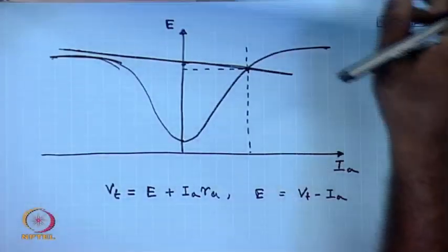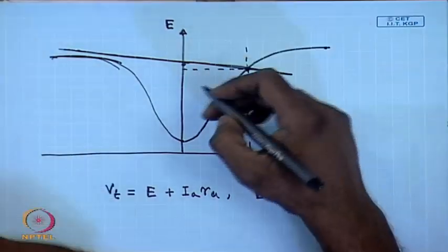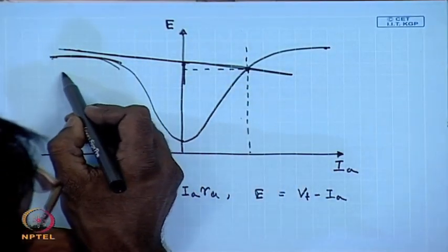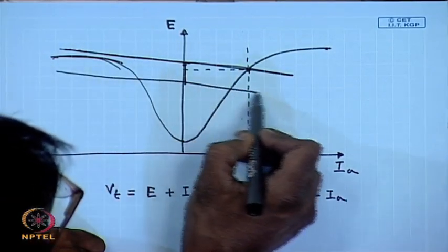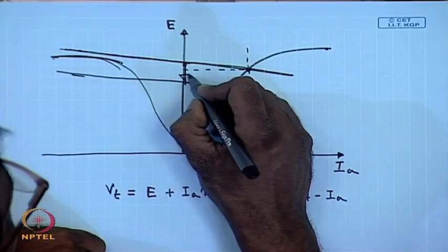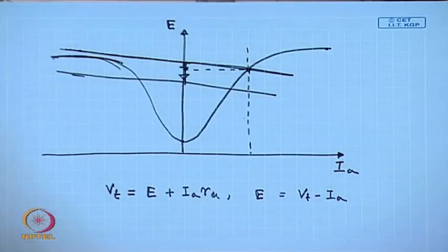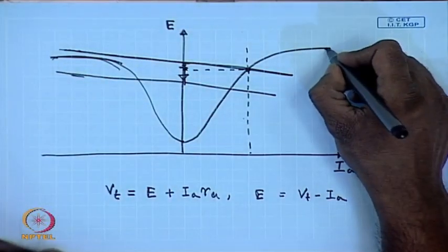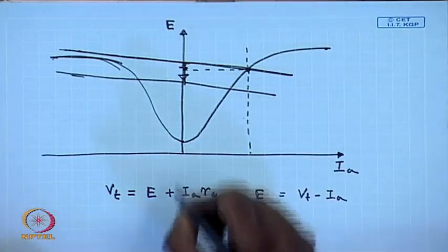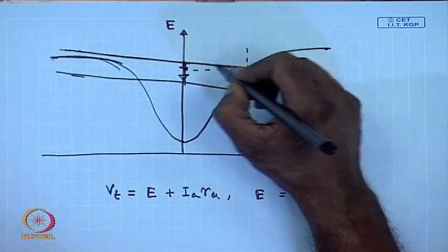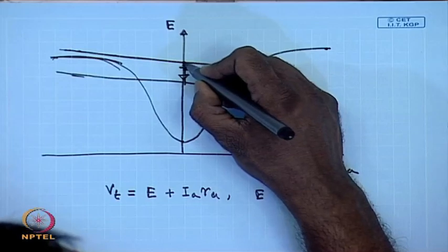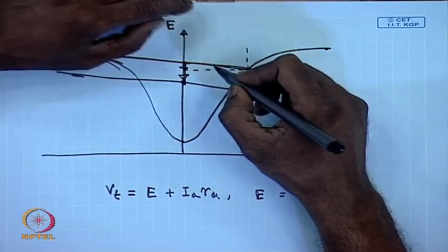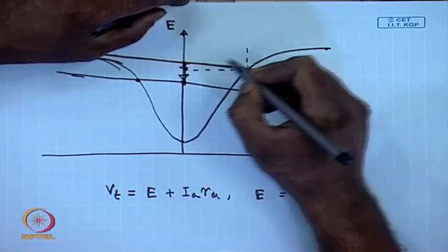The only way regenerative braking mode is possible is if by some means the load line during braking operation can be reduced. We will see again that this can be achieved by using an electronic power supply called the chopper. Hence, normally a DC series machine will not allow regenerative braking, but using a chopper you can go for regenerative braking of even a DC series motor.